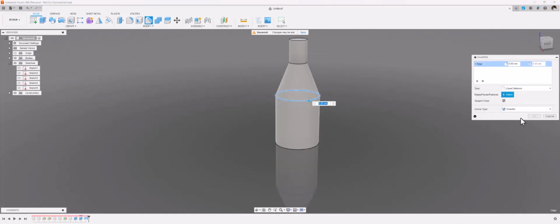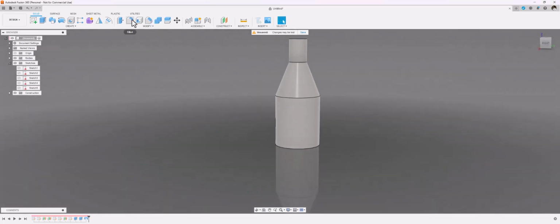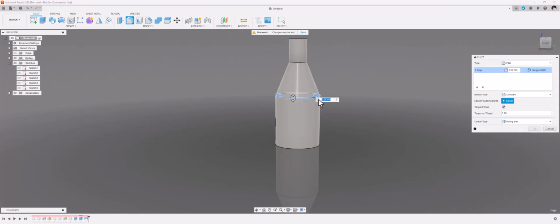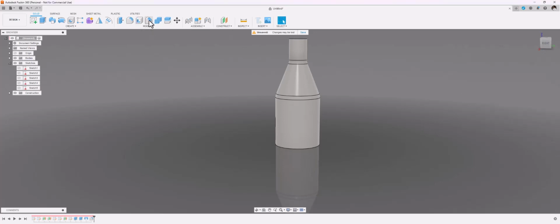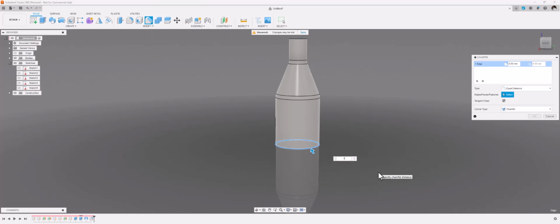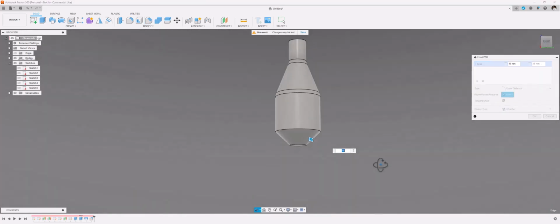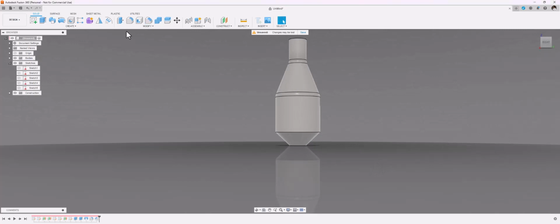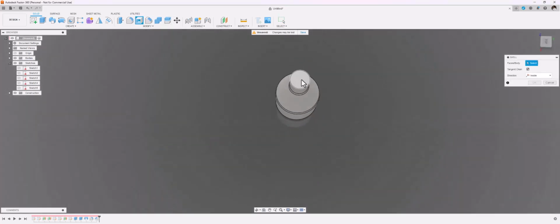Okay, so again we could hollow it out if we want. I'm not going to do that just yet. Now I can use a chamfer, which is a straight line here. That's not quite what we want, so we do actually want to fillet it. Let's put 12 there, and also include that line, so those are both 12. And then let's chamfer the bottom, which is 16. Gives us the diagonal line like that. And then shell here. And again, that's wall thickness.